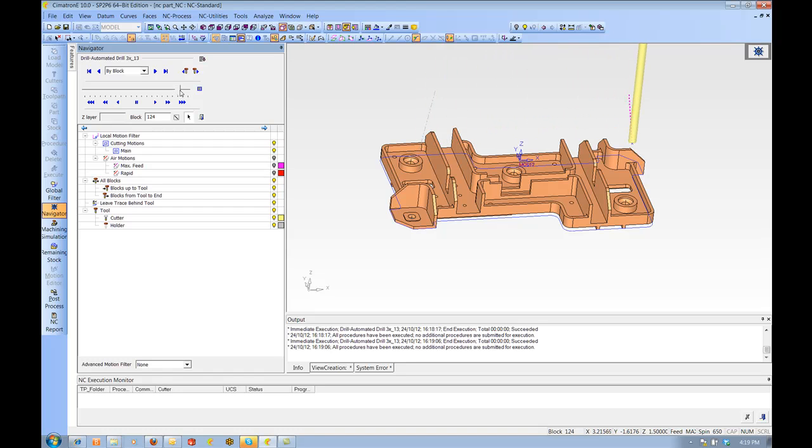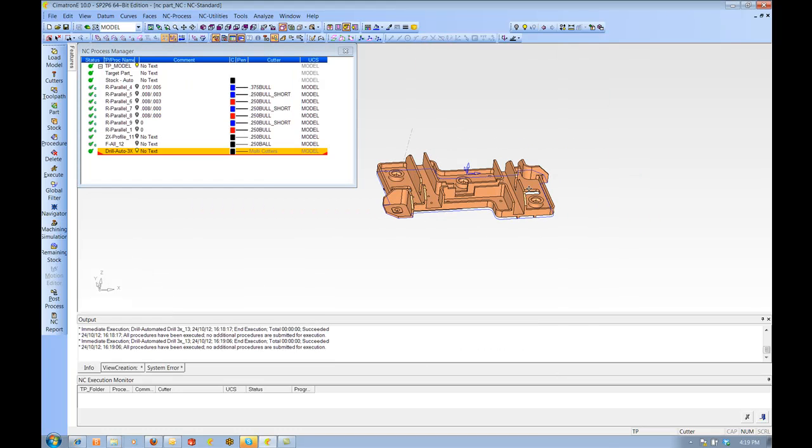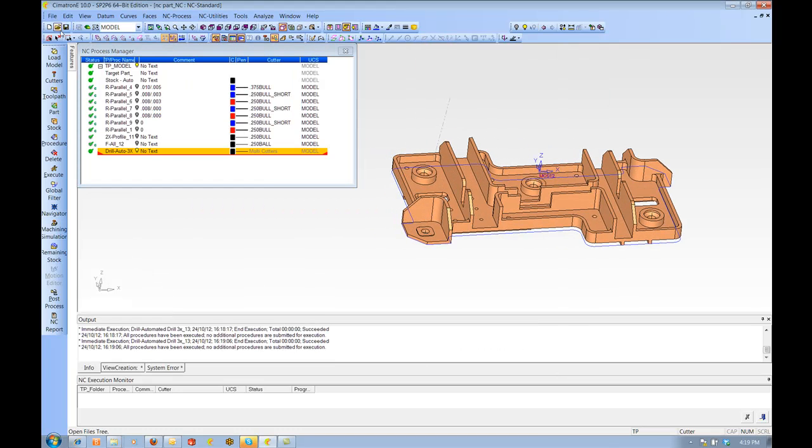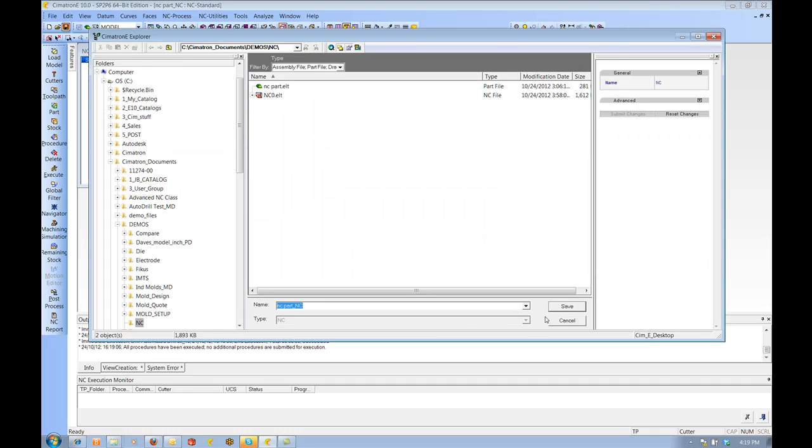And whatever process you assign to this is the appropriate process. So like with that reamed hole, I believe I sent an end mill in there to straighten the holes out prior to bringing the reamer in. So however you program something is the appropriate way.